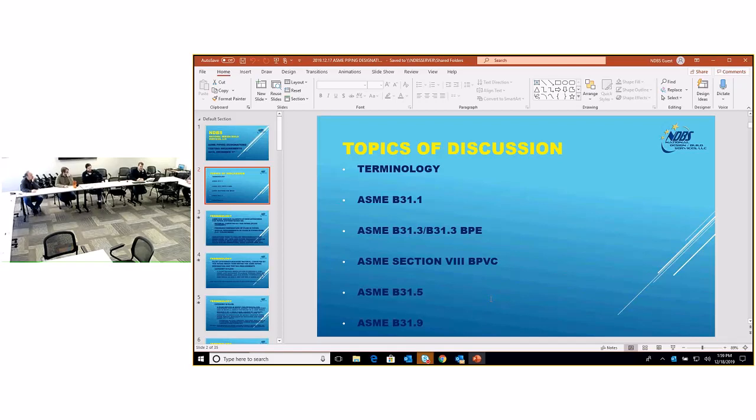My initial assumption was that our hot oil or our building heating system was a B31.3 system because the process temperature is over 400 degrees Fahrenheit. So if there's a failure of a valve, my thought was, oh, the temperature in that heat exchanger is going to quickly come to boiling. And for a sustained period of time, I could circulate that around the building and create risk all over the building.